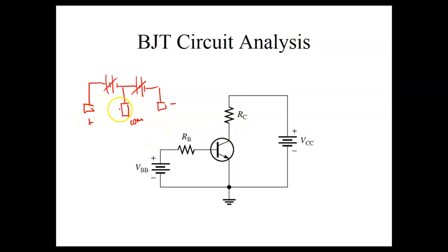We can use one of them. So notice this: on this one, we would have to have the minuses connected together. Well, with our trainer power supplies, we can't do that. So when y'all wire up this circuit, you can use one of the trainer's power supplies for this one, and then we would have to use another power supply for the other one. And that's where those other power supplies that I'll show you would have to come in. We could use two trainers, because on the trainers, this is not a ground.